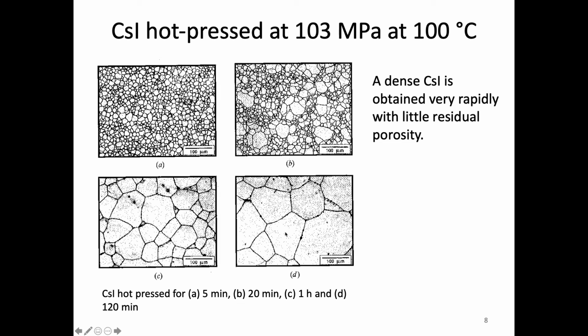After that, all we get is grain growth. This is, for the most part, typically not desired, but there are some applications. For example, these very large grains are probably better for the translucency of this material, so this might be a very translucent or transparent material. For the most part, this isn't going to help with strength or toughness, but there are some optical advantages to doing this.